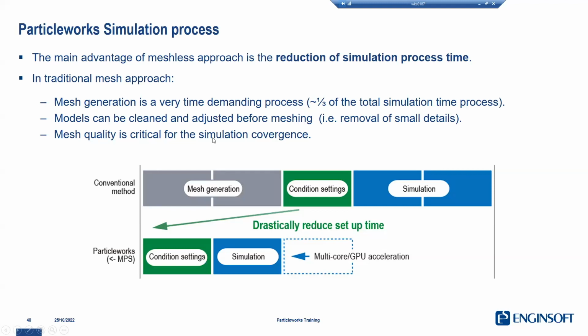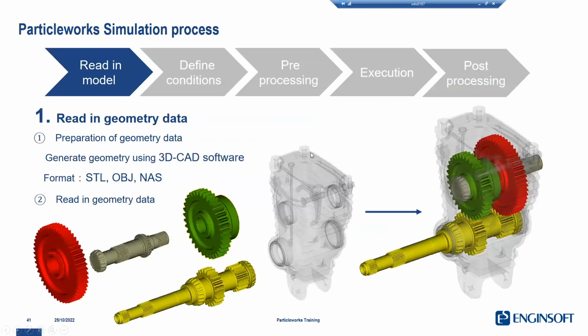So usually it's quite stable, our simulation workflow. What you need to do in the workflow is to start from your CAD. You want to export in STL, so surface type of surface geometry, or OBJ, also Nastran formats, and you want to export without simplification of the geometry from the CAD.